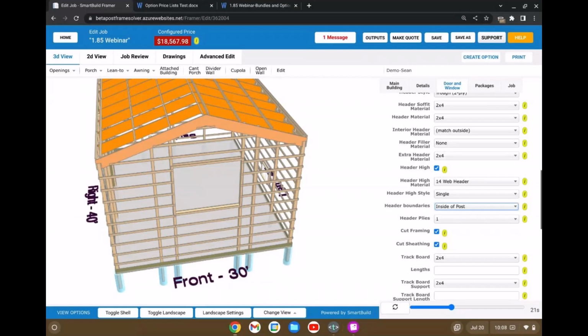Okay, yeah, got it. That makes sense. And would that necessarily be on center with the standard posts? Yeah, we would keep them on center. We typically just basically behave the same as the eave posts, which are sticking there because we have a truss above them. But that's how we typically handle it on a gable as well. Just keep that layout.